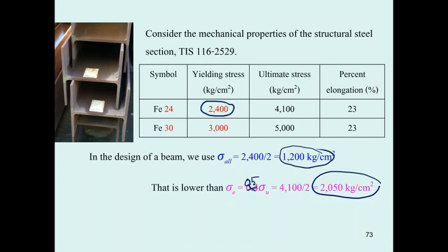However, you have to be very careful when you have welding. When you weld, the beam is usually very long. Maybe you have a piece of 8 meters, and then you weld it with another 2 meters. If the welder is very good and has a special way to cool the welding, that's going to make the weld homogeneous with the steel of the beam. But if the welder is bad, sometimes they just pour water onto this weld and cause cracks in the steel over here, and that is very prone to fatigue. So beware of the quality of construction when we talk about building a steel bridge by welding.